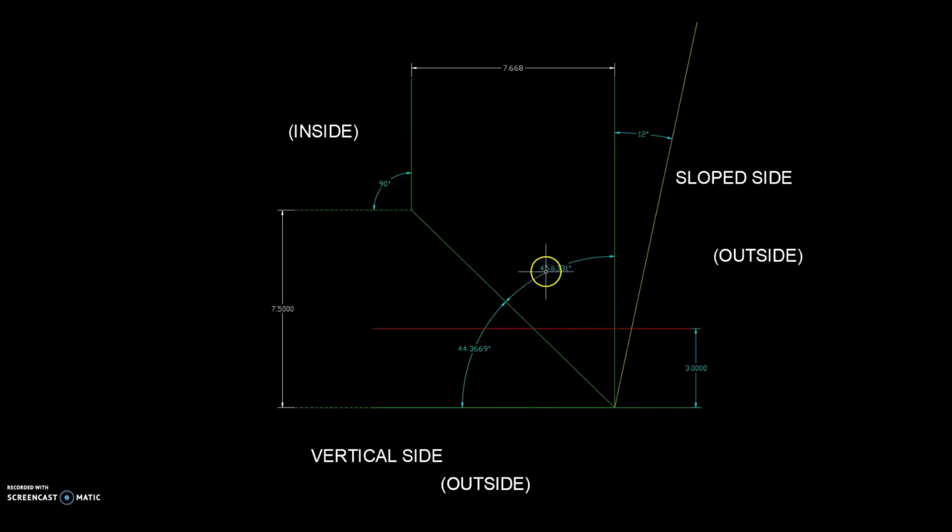While we are still looking at this image, let me say the next step will be copying the bottom footprint, moving this toward the right, using the intersection of the face of the slope side with the red horizontal line as the base point. I'm placing this at the intersection of the top footprint, red line, with the slope line.